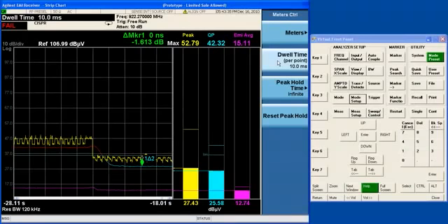So let's, for example, say that you have a 1 RPM turntable. That means you're doing 6 degrees per second. So I would like to get more than 6 points per second, say, to make sure that every degree of rotation is captured by at least 1 point. So a 10 millisecond dwell time gives me 100 points per second, so that's plenty fast enough to make sure I have 1 point per degree. In fact, I'll have about 16 points per degree.